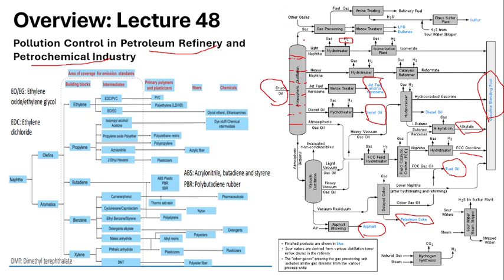Okay. So this is about the intermediate product and the bottom product. Now coming to the top product, from the top the gas molecules are collected and the gases are processed and Merox treated. Finally, the gaseous products are collected here as LPG, liquefied petroleum gas, and butanes are obtained as the finished product. And then the fuel gas undergoes the amine treatment.